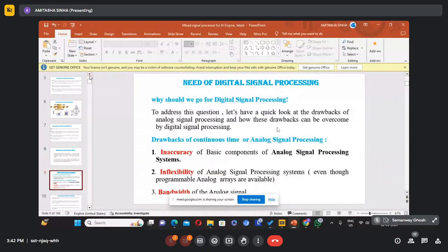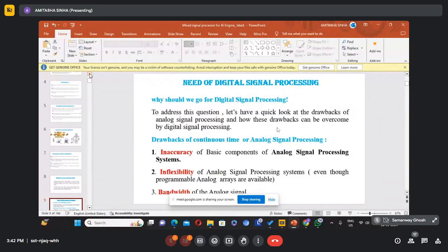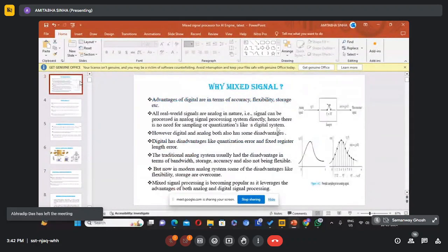Let's see, I have got some slides. Now, look at this diagram, the bottom diagram on the right-hand side. The analog signals are sampled at a regular interval capital T. So these are the sampled signals. But sampled signals are what? Still analog or digital? Analog, sir. Still analog. So we can call them discrete analog.